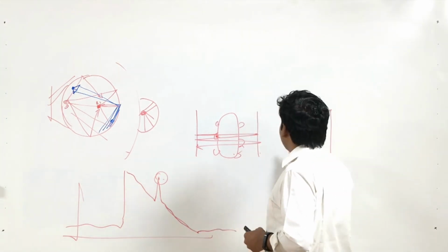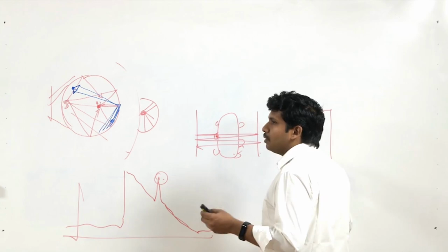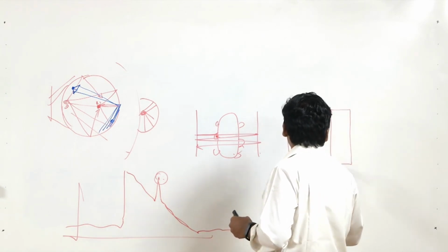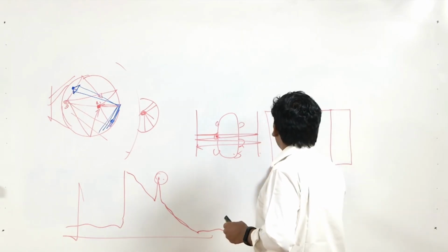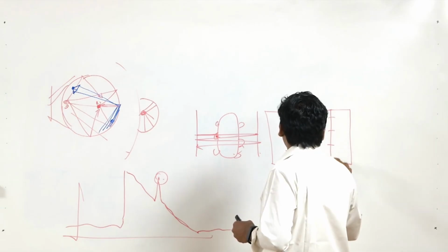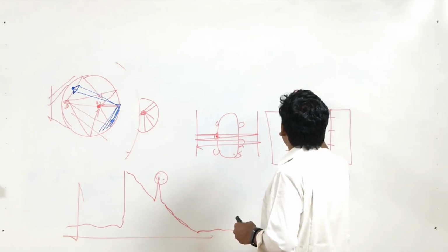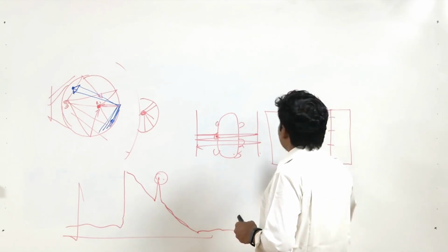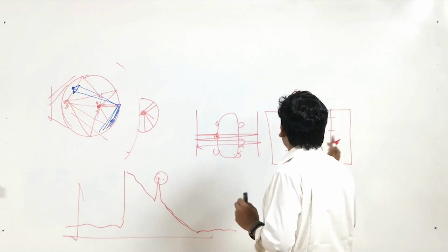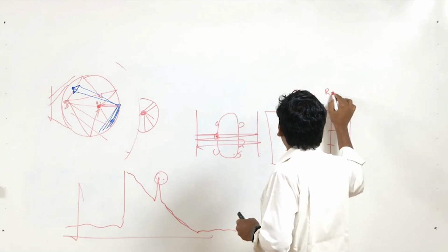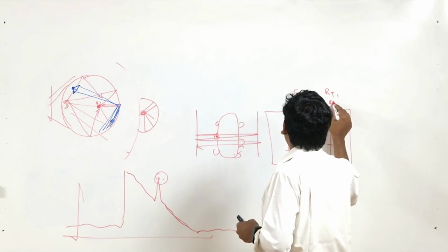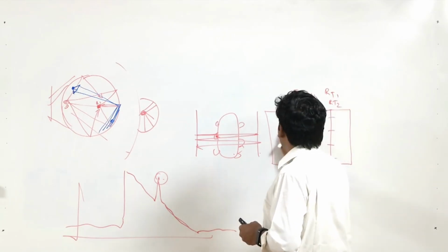If you cannot treat it too much or cannot do much around it, then you create an empty space here, create a lot of voids. You can keep them closed for one of the functions, say event 1, when you have a specific desired reverberation time; you keep these closed, you get RT1. For event 2, you need RT2, so just open these up.